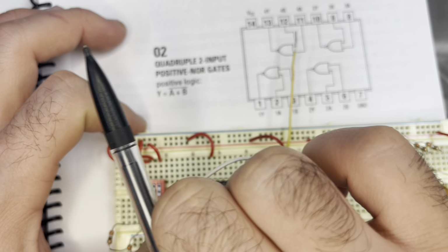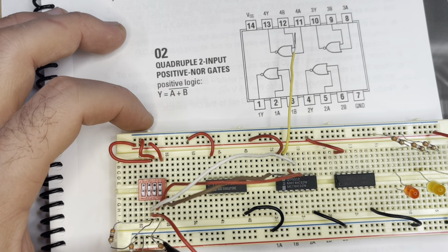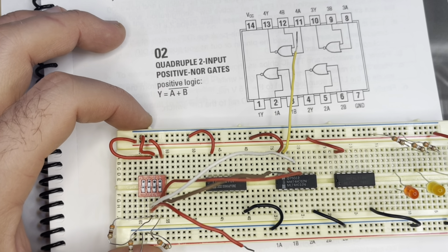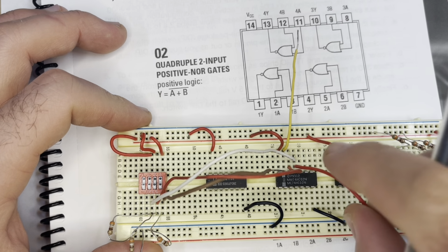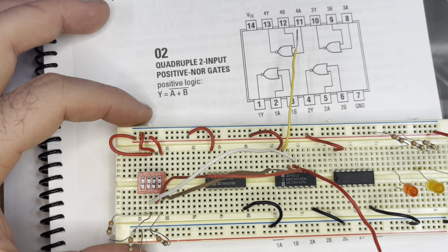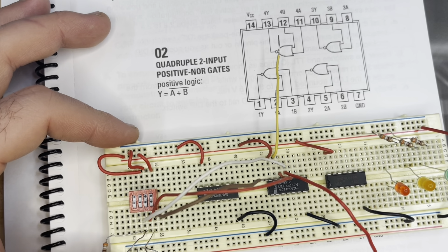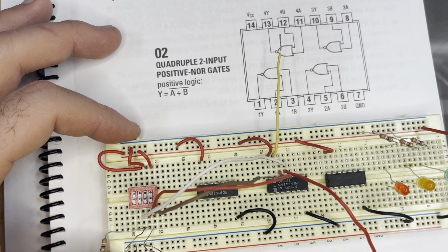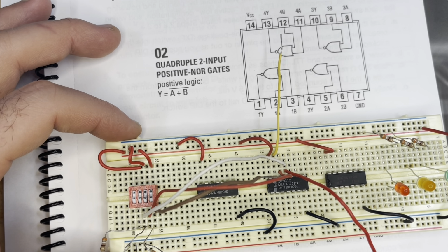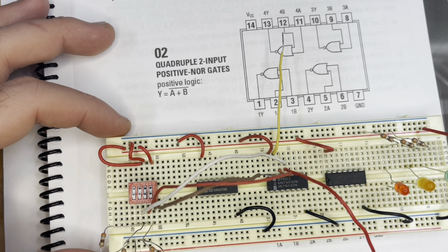So I have this A in order to shorten the number of wires that I need to use. I could go back to the switch and take it, but that's gonna increase the noise and also the resistance in the wires. So it's an easy way to take it from this point. Now I have A and C. Next I pick a gate on the same IC. I know that I need another NOR gate.